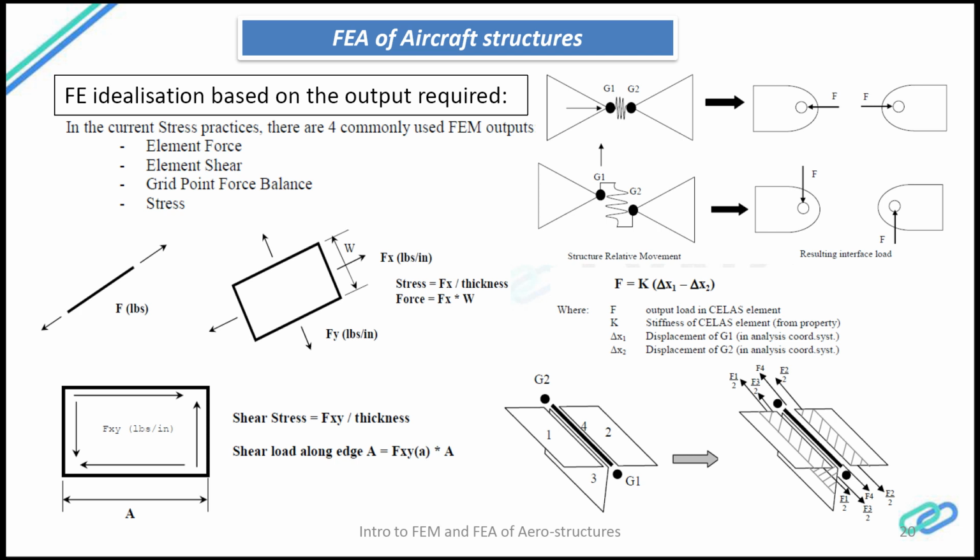But if they are a little bit vertically aligned, you get the vertical force, you don't get a horizontal force. So clearly that indicates there is some error. The user might have made a mistake, and it will be realized only after the post processing is done.